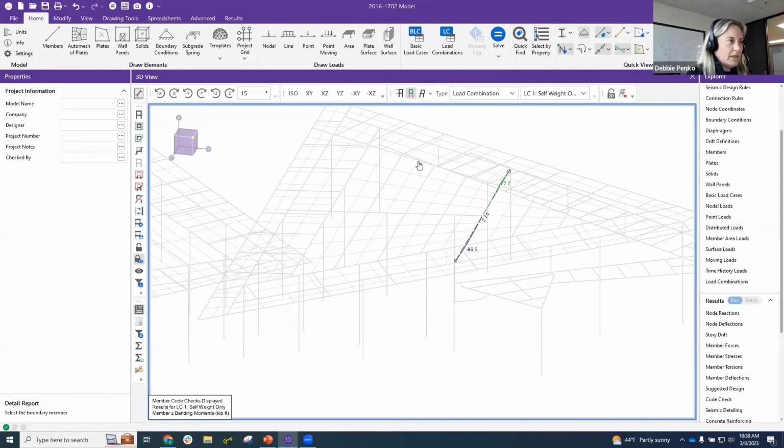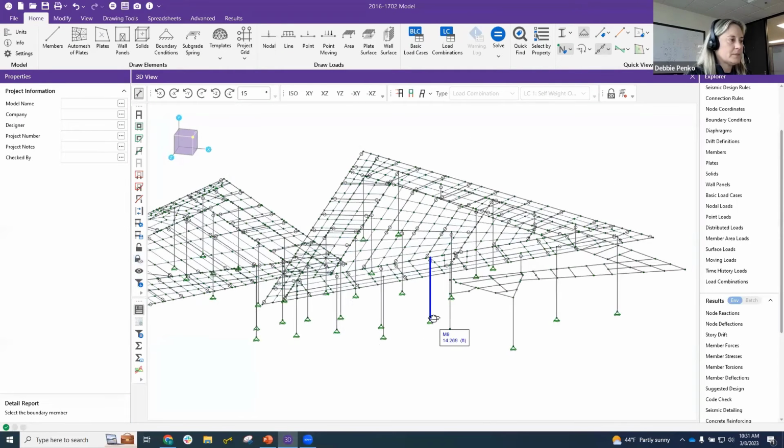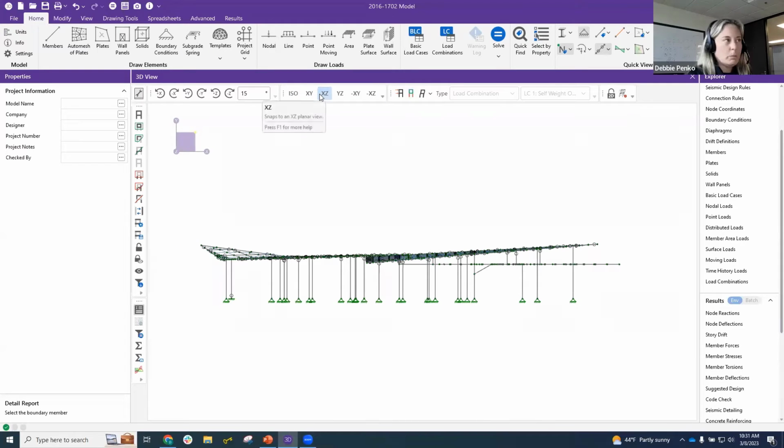And then we've got, lastly, if you're not familiar with this tool, I would definitely recommend spending some time getting to know our internal force summation tool. This was one of the ones where I would say it's really important to understand how to use it really well. Once you get a hang of it, it's a summation tool, and it cuts across your entire model. So you can take sections of the model and summate across them, or the entire model. If you use your internal force summation tool, you just click on that little summation and you click on a node and define a plane across that member.